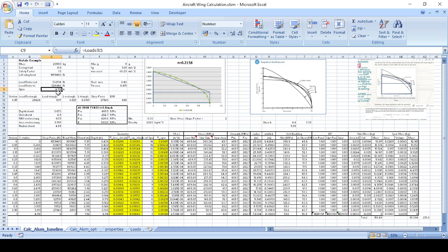My wingspan is 4.116 based on my scaling. So from that I was able to calculate my chord from the root to the tip, scaling linearly across based on this ratio. I've got my load bending, so it goes from 0 to the maximum bending moment, which you can see is the maximum shear force here, and then the bending moment is really a multiplication of a buildup of those forces and calculating the maximum bending moment up to that tip.